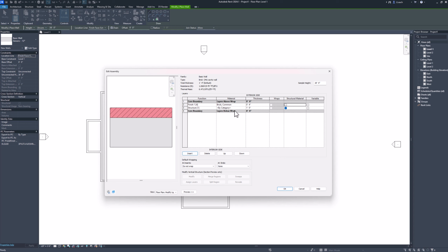So we've got that layer. And that layer is going to go on the top. So I'm going to select this number 2 and move it up. And then let me go down to here, I'm going to click on number 2 and then hit insert. That way our new layer is right underneath this one that we just created.